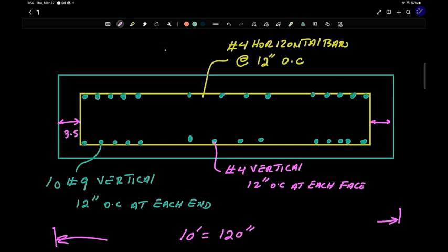We calculated d based on 0.8 times 120. But literally, if you take 120 minus 7 inches and then calculate that way, you end up with a smaller bar. So if this wall had vertical load on it, also being a bearing wall plus shear wall, we really have to calculate the area of the flexural steel, and that would be basically using the interaction diagram, which we've done before. But good luck, and hope you liked it.